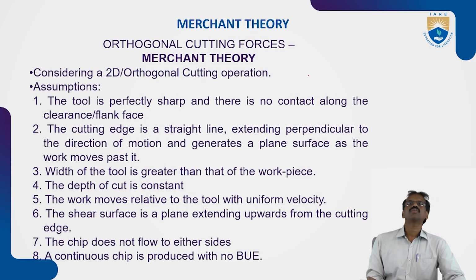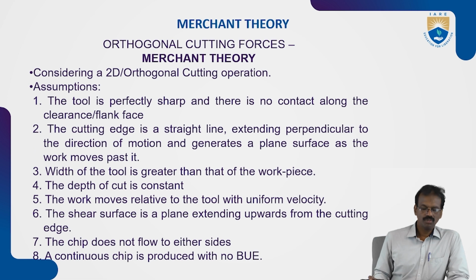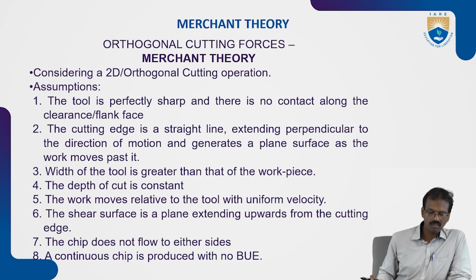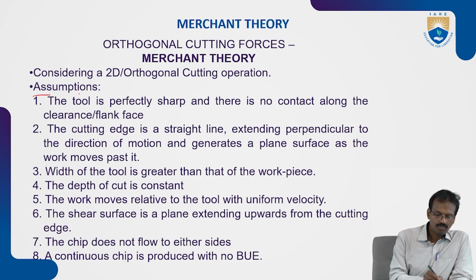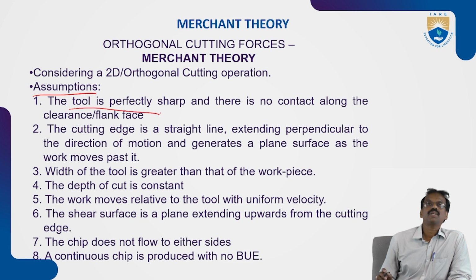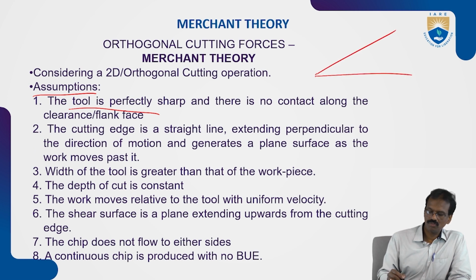Okay, so to understand this, or to use this Merchant theory to find the different cutting forces in orthogonal cutting, we have to take some assumptions. So we'll see what the different assumptions in orthogonal cutting are. So the first one: the tool is perfectly sharp. Okay, so there is no contact along the clearance and flank. So this is the tool, you know this one.